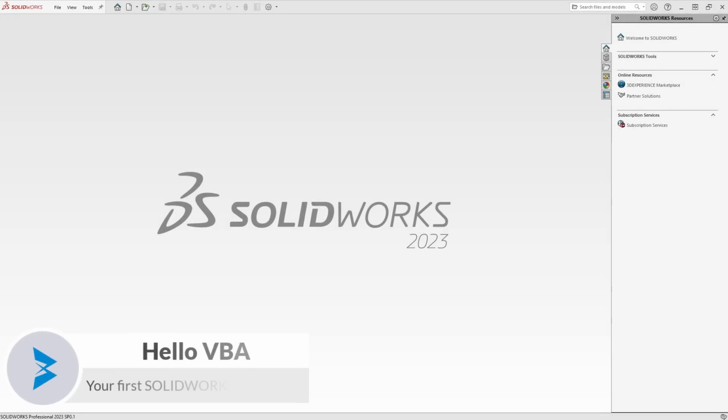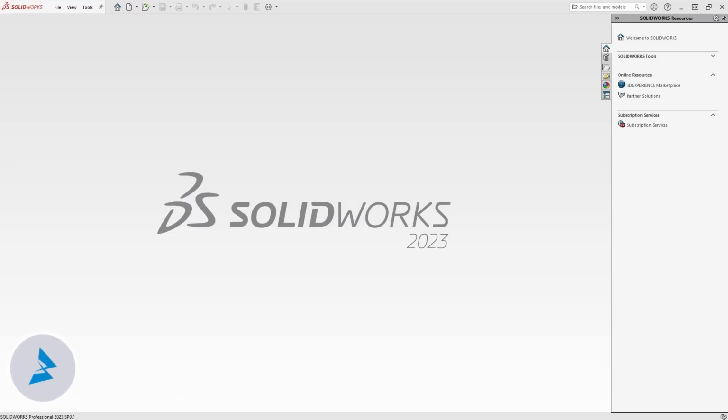In this lesson, I'm going to help you write your first VBA macro in SolidWorks. I'll guide you step by step through the process of creating a simple macro that outputs messages using 3 different scenarios. The first one is going to use a debug print that's going to show a hello world or hello VBA message in the immediate window.